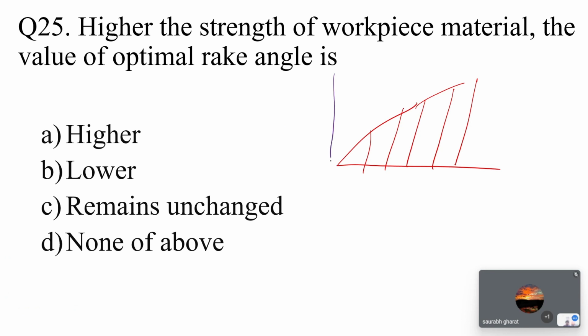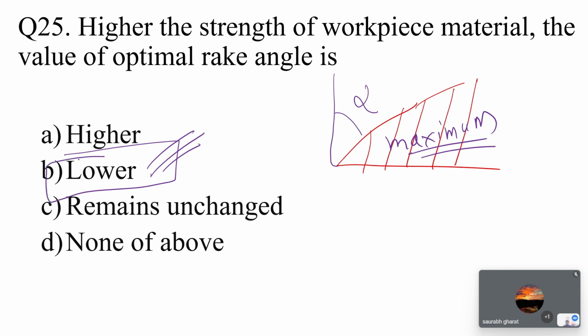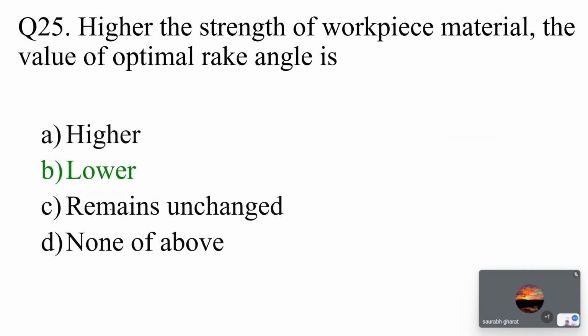This rake angle must be lower because we need to maximize this area. It is mentioned here: for higher strength of workpiece material, the optimal rake angle is lower.